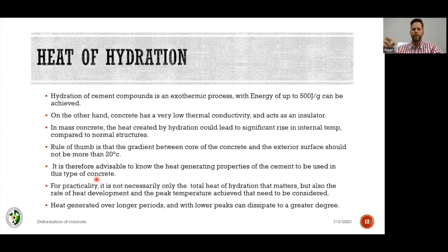And then they graded the aggregates down, and the larger aggregate also contributed to a lower paste value or a lower paste component. And there's less surface area to cover with paste. So you also have less risk of hydration and of shrinkage, and the list goes on. So they took it to the ultimate. And in order for you to test this cube, you cannot take a little 150 by 150 cube, and how many fists will you get into that little cube mold? You probably get 3 in there, and then you are stuck.